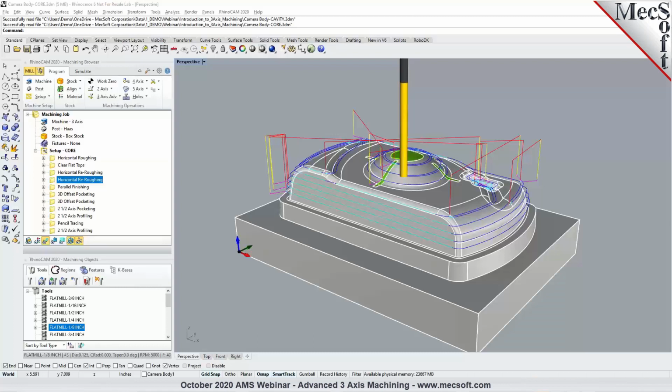And so in those kinds of situations, you're going to run into jagged toolpaths, because the machining algorithm is thinking, oh, the cutter is touching in multiple places, and then it moves to a different location, and it's not touching in so many places, or maybe not touching at all, as in the case of a very variable radius fillet. So those are things you need to keep in mind when you're using the pencil tracing and valley remachining methods.